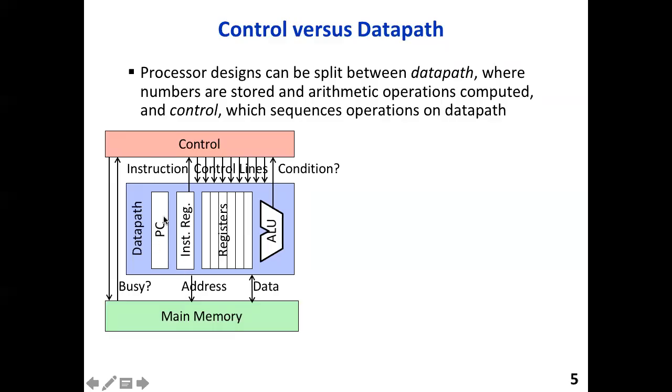And then we'll have a thing called the program counter, which is kind of like your finger keeping track of where you are in memory. And every time you go to get another address, you'll be incrementing the program counter. And if somebody executes a jump instruction, you'll be jam loading the program counter, so you'll jump to that new address.